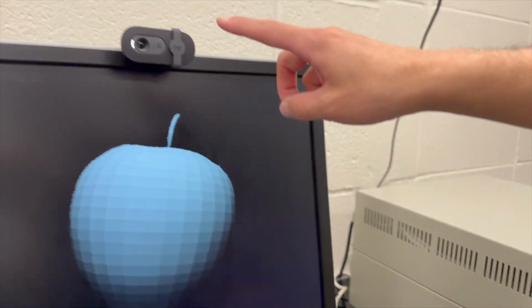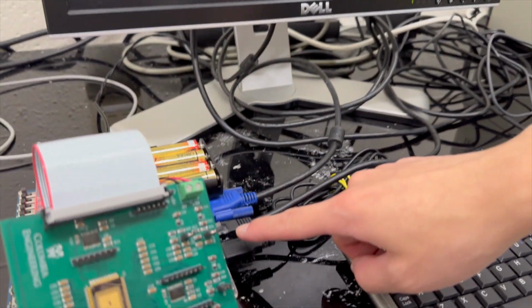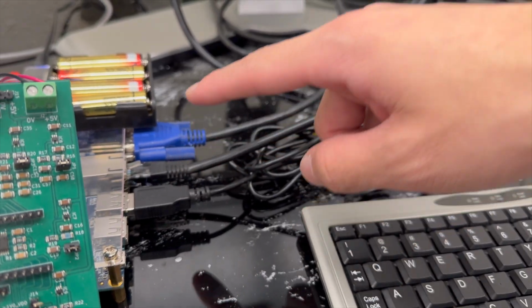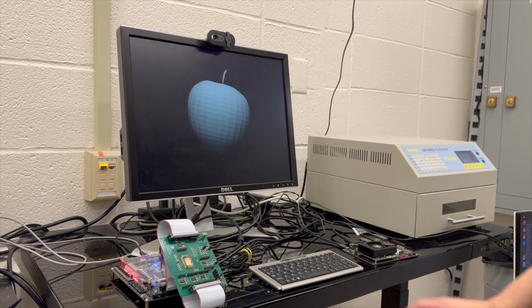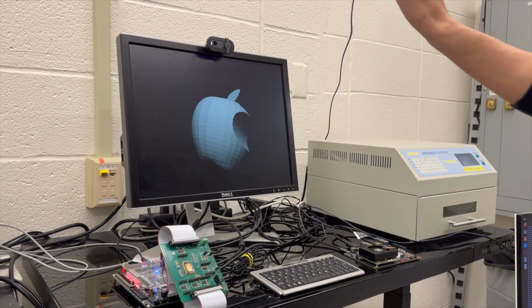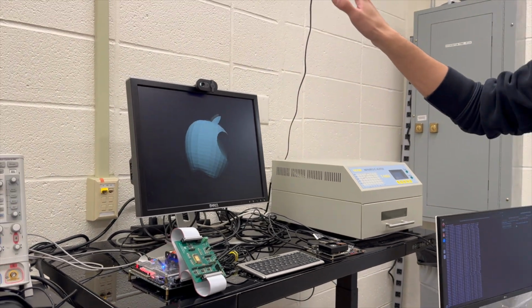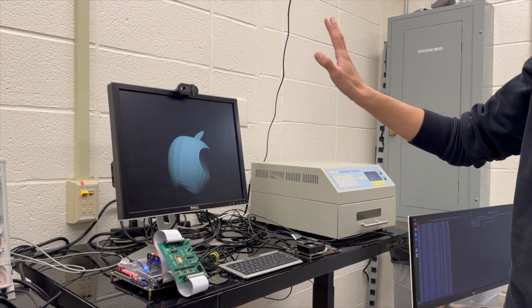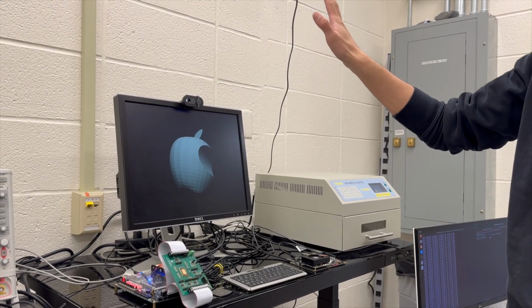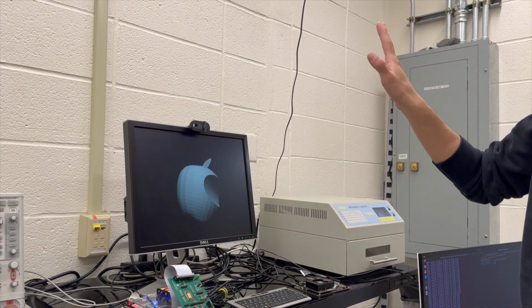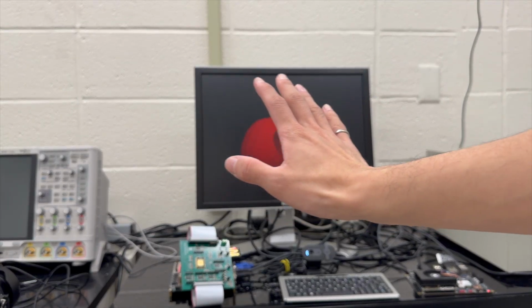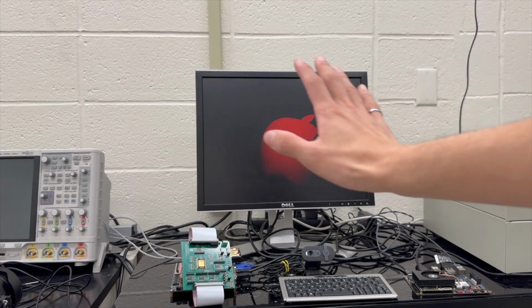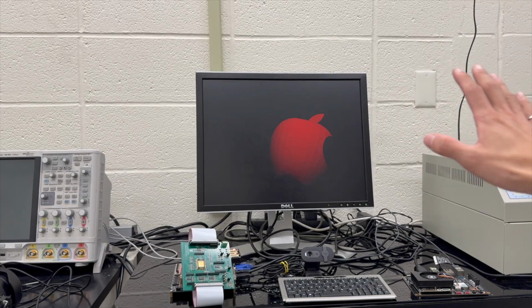Furthermore, other than just keyboard, we have another interactive way to control our chip, integrating a hand recognition system. Another PC is running the hand detection program, and it will forward the commands to the FPGA through Ethernet and eventually controls our chip in real time. And this is a better angle to look at how the movement and orientation of the hand actually control the object in real time.